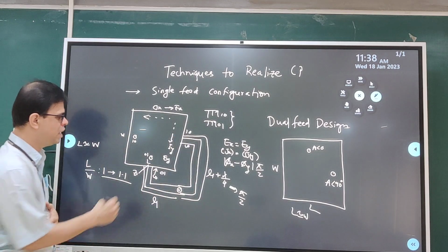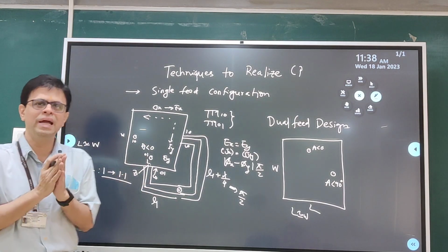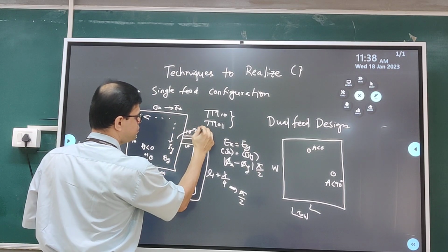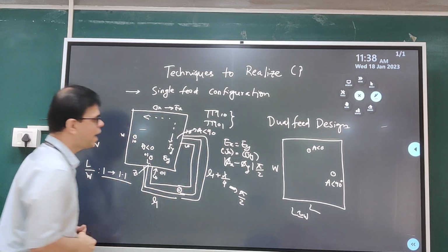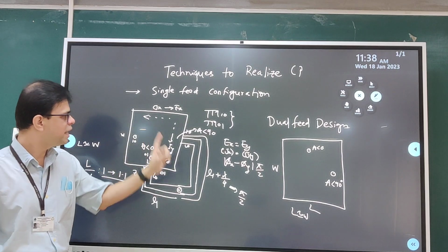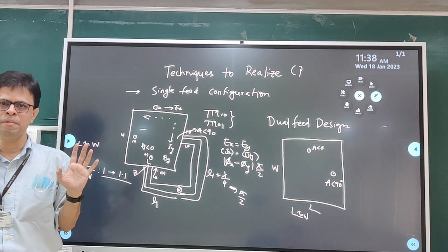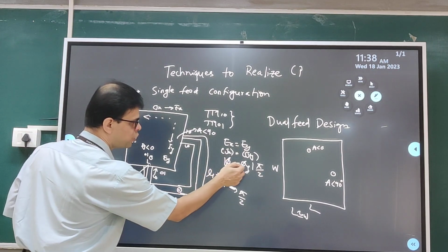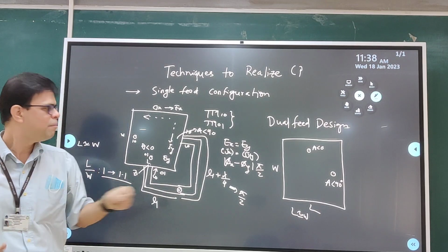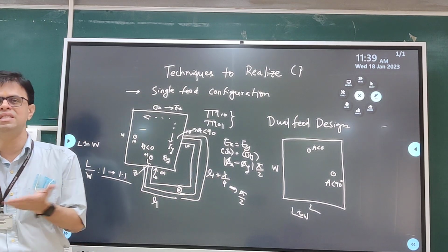So effectively at this point I am exciting, say, amplitude A with angle 0. I am neglecting the phase introduced by L1, and I am introducing the other signal as A angle 90, because the effective difference in phase is 90. So by exciting orthogonal modes, I have ensured that Ex and Ey are excited, and then by ensuring the power divider network adds the appropriate phase difference through the lambda by 4 length, that ensures a 90-degree phase difference between Ex and Ey.